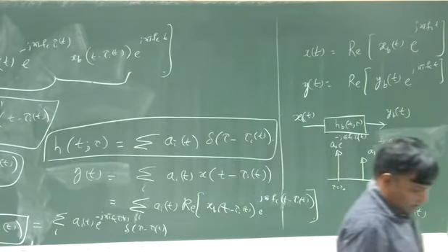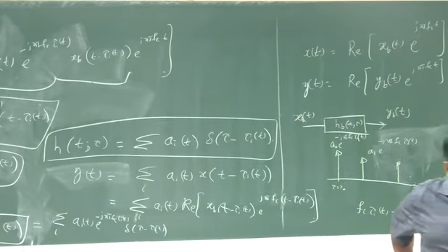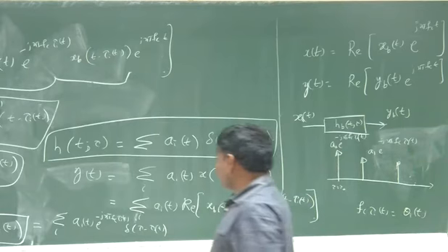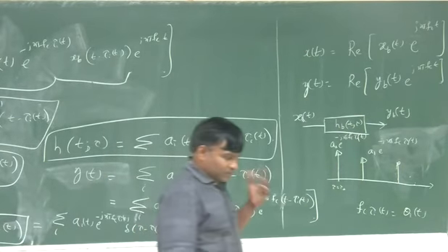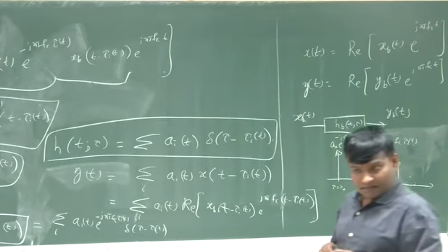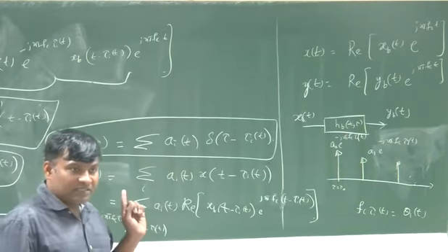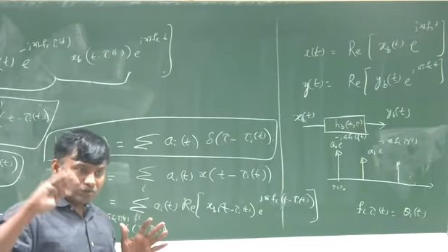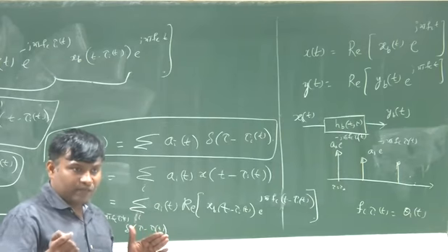But of course, if the time variations are too rapid, then it's not such a desirable situation. If the signal is transmitted at rate 1 over T and the time variations are on that order, it will be very difficult for the receiver. Usually these variations are so slow that for one time slot, you want to transmit a packet.